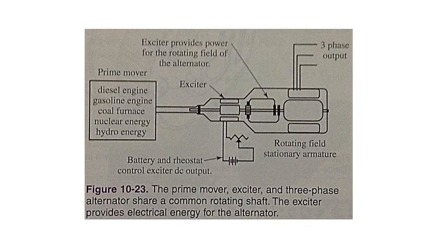The alternating current generator. The AC generator is like the DC generator in many respects, with one key exception. The commutator is omitted. The ends of the armature coils are extended out to slip rings. Brushes sliding on the slip rings provide connection to the coils at all times. The current in the externally connected circuit is an alternating current.